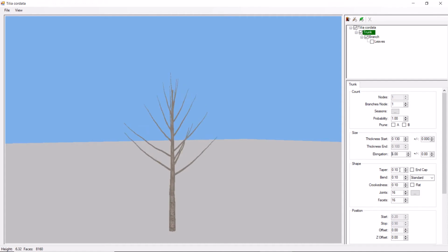How are we going to use these species? In Land Design, it will be there where the height is defined with a specific unit of measurement. What matters most to us here is achieving the correct shape and proportion of the representation. Moving on to the shape field, the first parameter allows us to gradually thin the trunk along its length. With a value of 1, the trunk will maintain a uniform section, but if we reduce this number, it will become thinner towards the end.